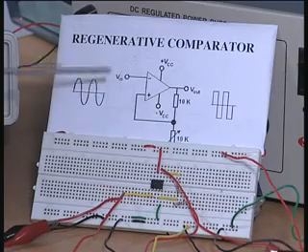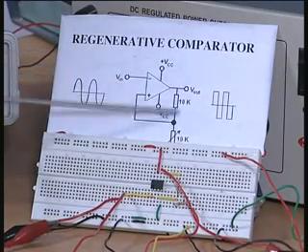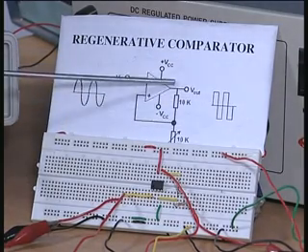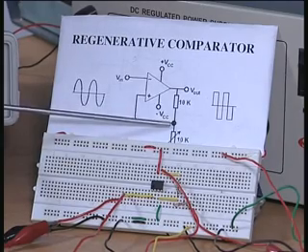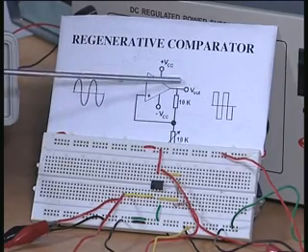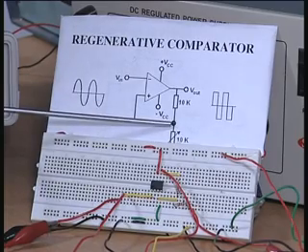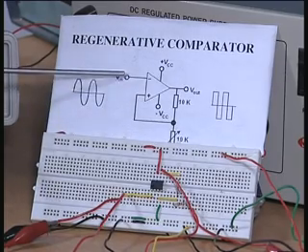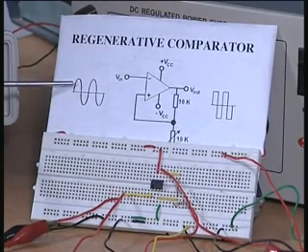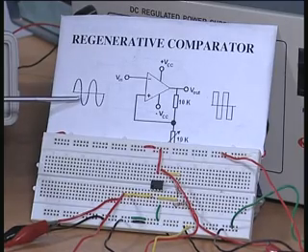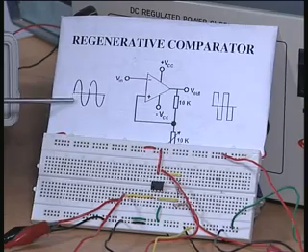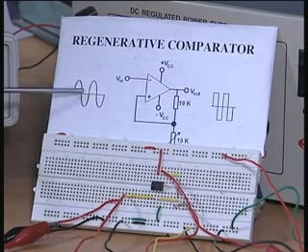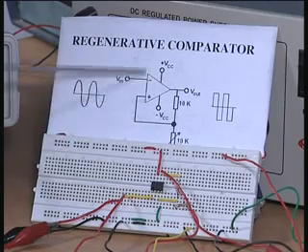But now what is going to happen is, because it is a regenerative comparator, whenever the output is plus Vcc, this point will become some beta times plus Vcc, and when it becomes minus Vcc, the reference point becomes minus beta times Vcc. Therefore whenever the input voltage exceeds plus beta times Vcc or goes below minus beta times Vcc, there will be a transition, instead of plus or minus 150 microvolt as we had in the earlier cases. So that shows that it has got a hysteresis.